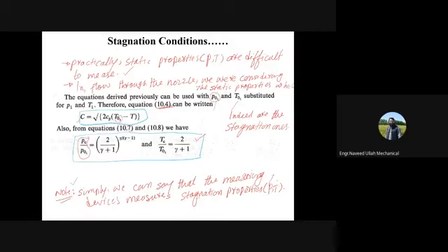If you have pitot tubes or thermocouples, they measure and give you the stagnation temperature and stagnation pressure. Yes, if you have the measured stagnation temperature and you know the initial velocity, then you can calculate and find out the value of T1, and you can use the same formulas, but it will be better if you alter those formulas for this case.